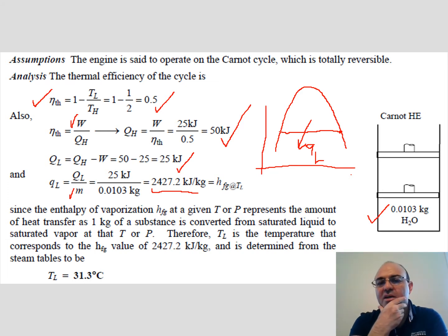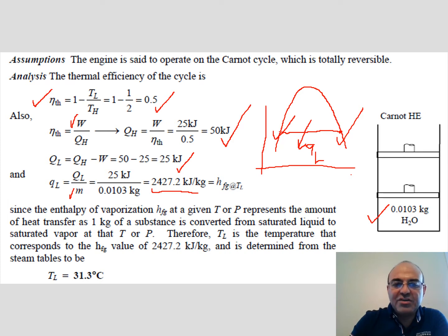Okay. So what does it mean? You remember from previous chapters that this QL is actually the heat of vaporization, right? This is the heat of vaporization, QL, because we are moving from the saturated vapor branch to the saturated liquid branch. So this QL is therefore equal to Hg, which is the enthalpy here on the right side, minus Hf. Therefore, QL is simply equal to Hfg.